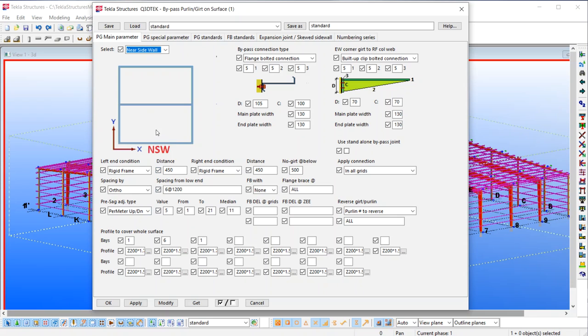To adjust sagging of main framing members, the purlin rows can be lifted or pushed down progressively, as required, between select purlins, with median purlin as the changing point. This feature can be used to create a smooth, shallow curved roof without using curved rafters.